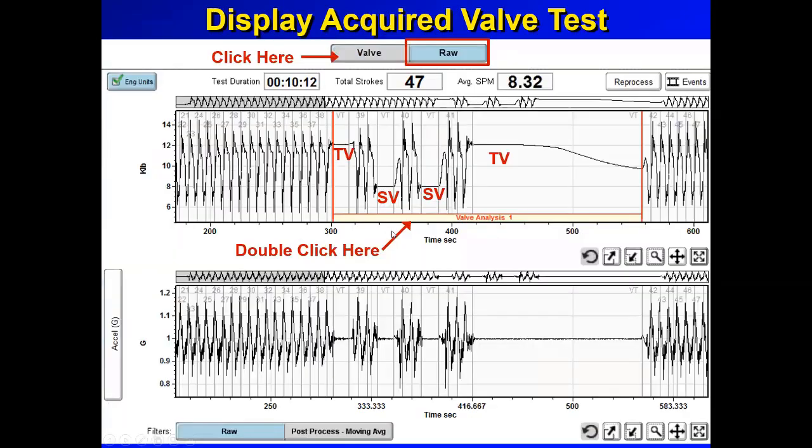Another indication of friction will be the dyno card shape. If you have a thick nose in the dyno card shape, that's usually an indication of friction. Surface card will also indicate if you have friction in the system. Friction may be from different sources. Even an over-tightened stuffing box will give you some of the friction as well.